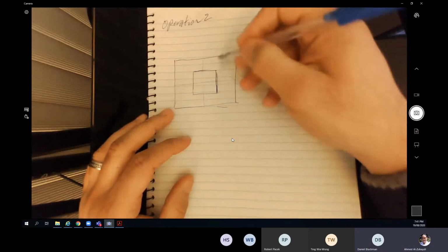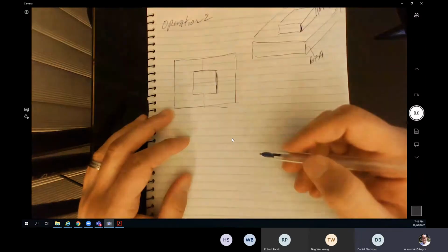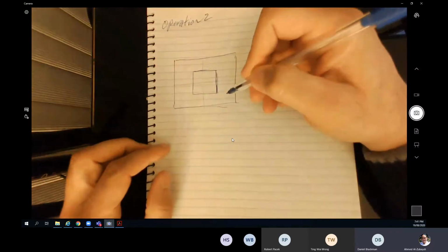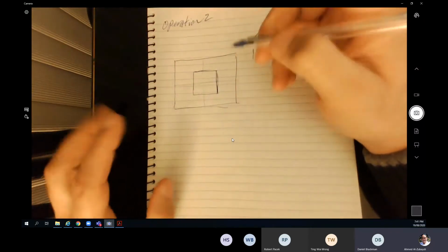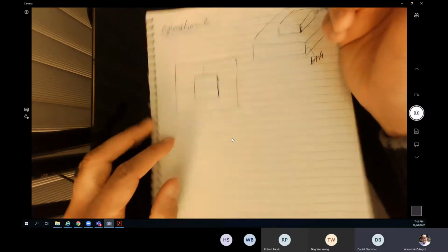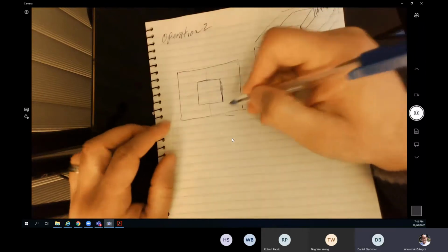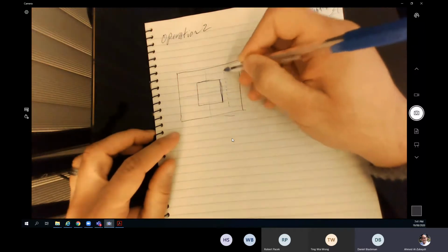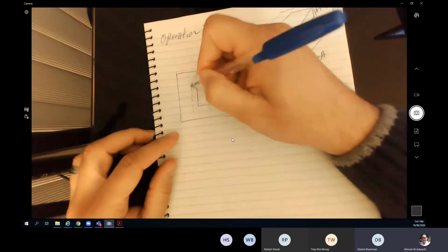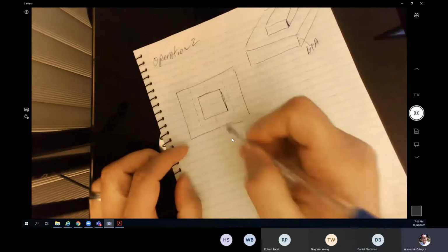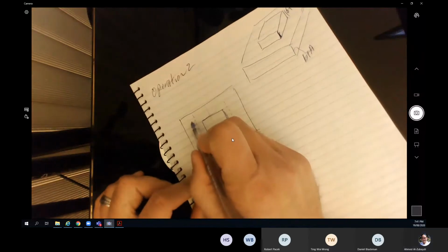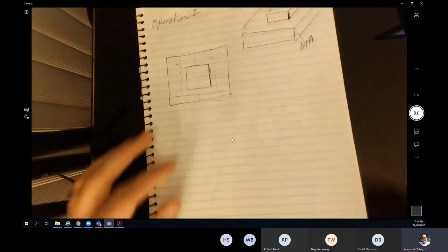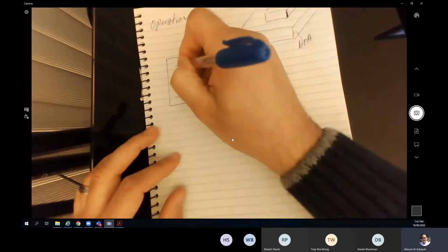So here we are going to have face milling, but around this part is going to have a profile. To make the profile, do I have to use the same cutting tool? I'm going to use a 12 millimeter cutting tool now. So I can make an offset line parallel to the square shape, offset by 6 millimeter from the original line. Same thing here. Okay, so I can find these points.